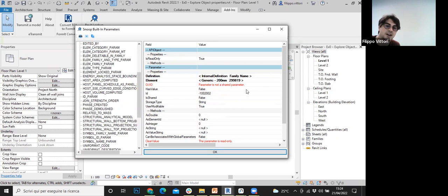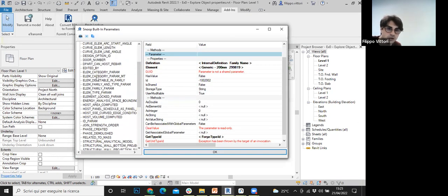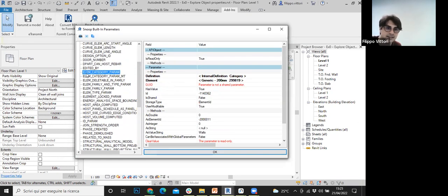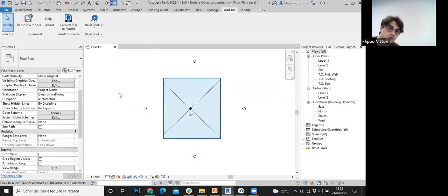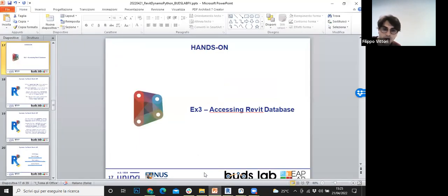And for instance, these are properties. So for instance, if you want to access the category, like thanks to a built-in parameter using the property as value string, in Python, you will simply put a dot and then query the method or the property, and I remember maybe it's a method of as value string. And this is also a very useful plugin to interact with Revit API.